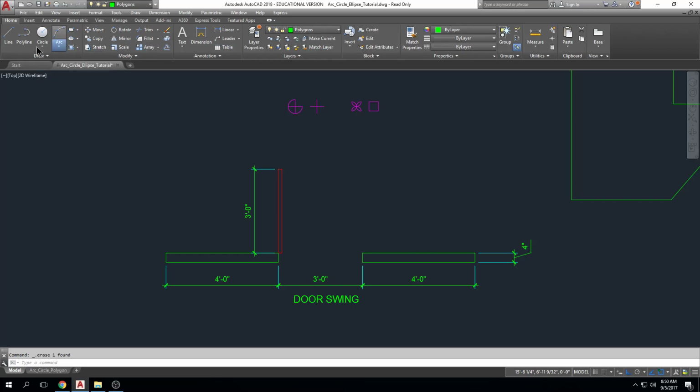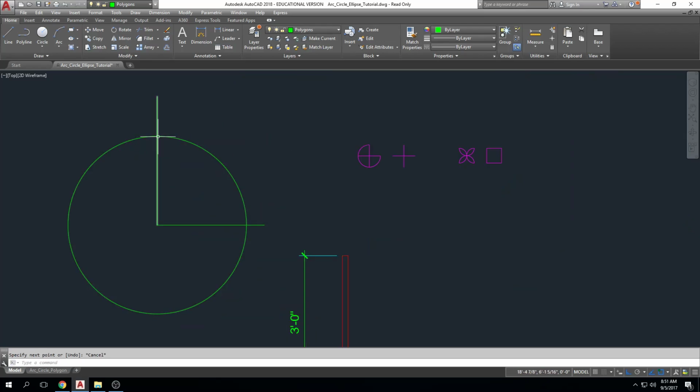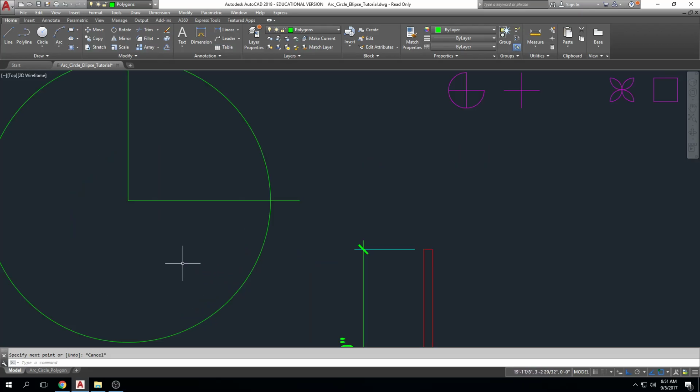So when you draw an arc, essentially, let me just remind everybody, let me draw some lines here. Okay, essentially this is an arc, right? And the arc is defined by a center, and it has a beginning or an end point here and a beginning or an end point here, okay? When we are working with arcs, they can be a little tricky in that there's a positive and a negative direction for your arc, okay? And it's the same as a polar input. So anything that goes in the counterclockwise direction is positive, okay? Anything that goes in the clockwise direction is negative. So you want to remember that.